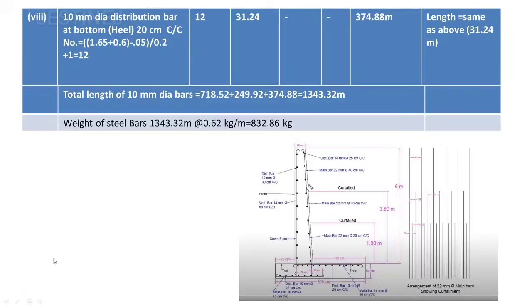And coming to the next case, here you can observe the 10 mm diameter distribution bar at the bottom heel portion. And here also the distribution bars are provided.